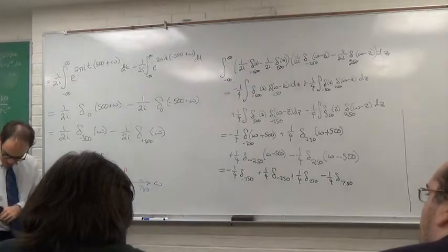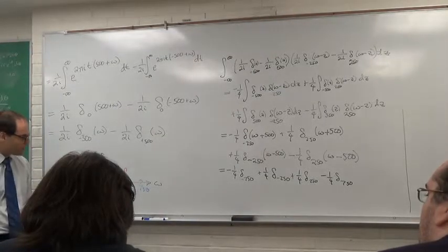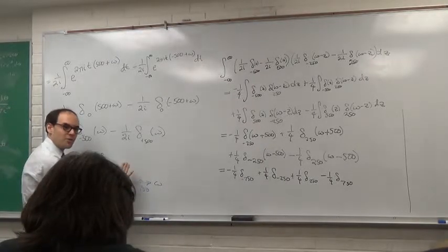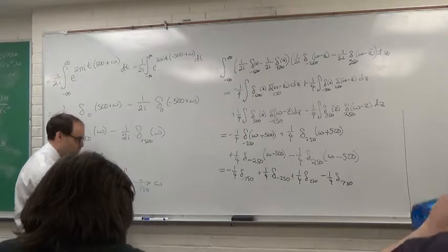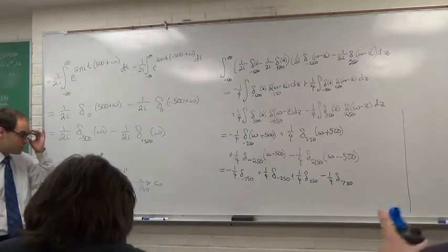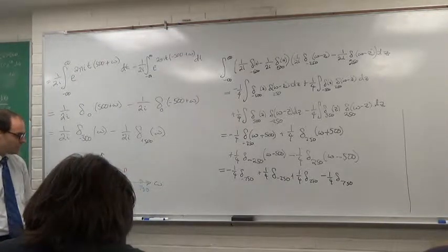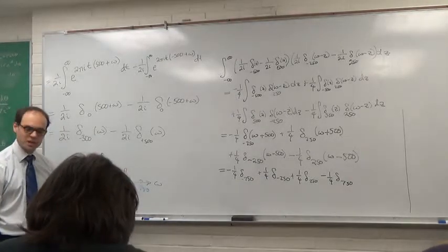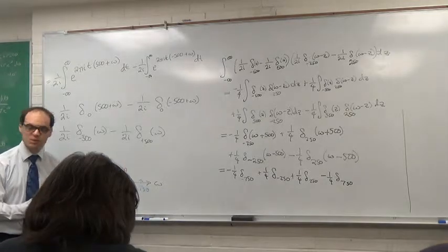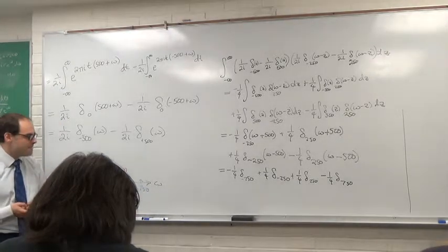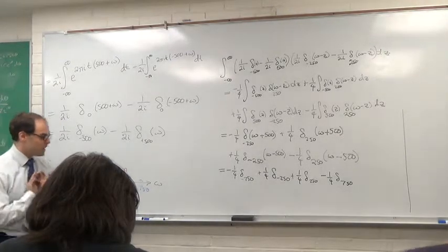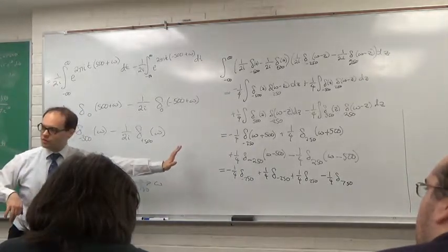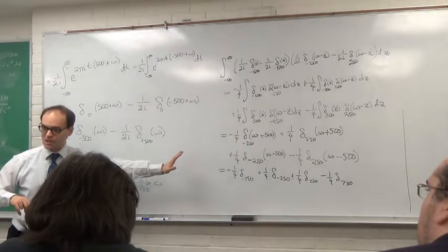So the point of the matter is that when you're building radio systems, you'll often isolate and get rid of one or the other of these, so you can control the position of the other one without messing with things. In fact, if you build a radio that does this mixing operation, as electrical engineers call it, taking products of two functions, you end up with a lot of stuff at much higher frequencies and some at lower frequencies. If you do not filter them out, you can get in trouble with the FCC, actually.